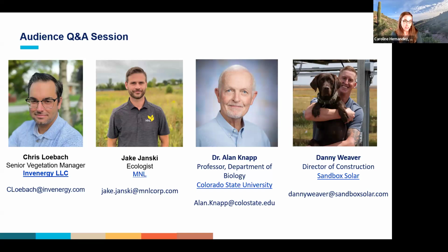Chris, do you decompact your soil? And if so, how and when during the project's cycle? And do you ever use different types of mulch depending on the climate? Yeah, so decompaction is an intensive activity, so we try to keep it only focused where it's needed, and that's usually going to be high traffic areas and lay down areas. We'll find those locations where we have heavily compacted soils, and we'll focus decompaction there. Most of the site, it's not necessarily a concern.